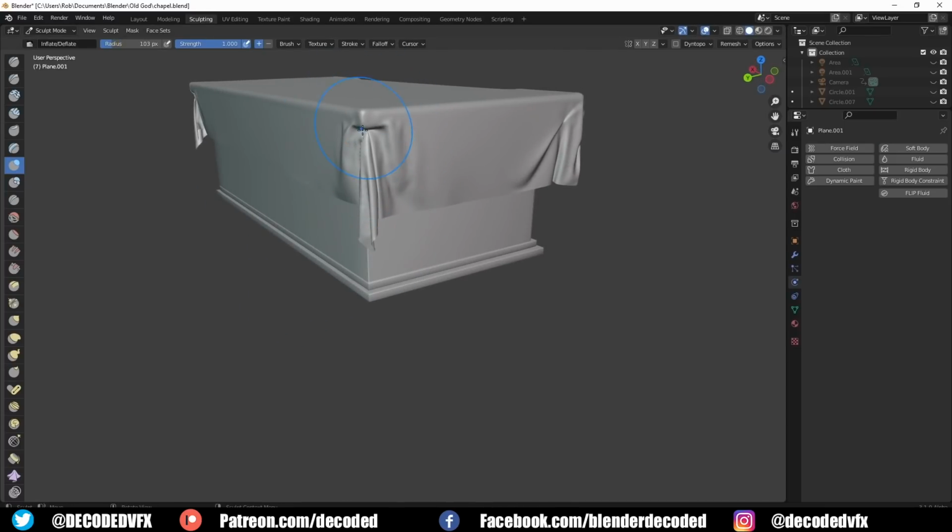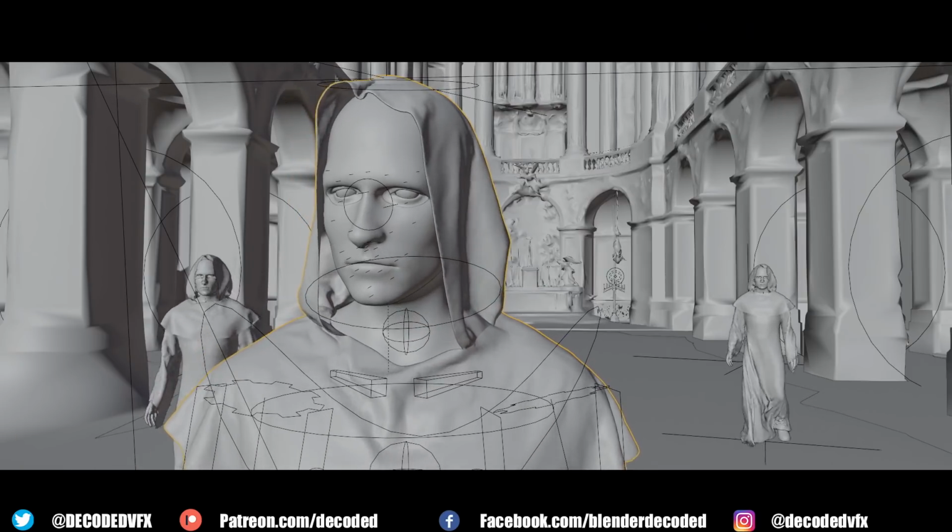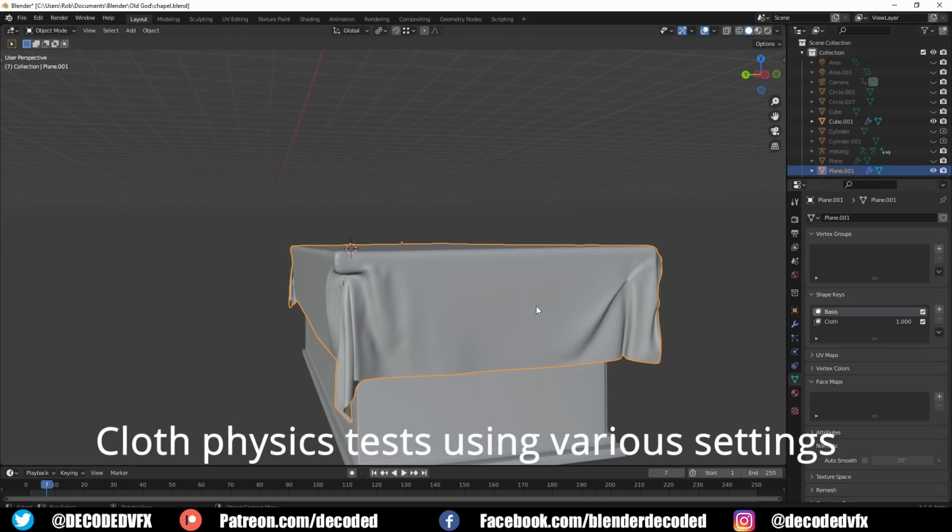I think it might be time for me to permanently move over to Marvelous Designer for cloth simulations in the future, because I don't think the Blender system's up to scratch for anything advanced. Character animations tend to look really jittery, self-collisions often cause the cloth to basically explode, and once a character clips into the cloth mesh it just refuses to let go.